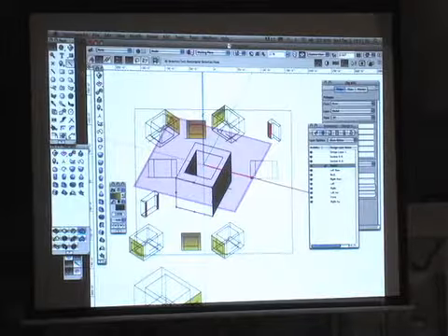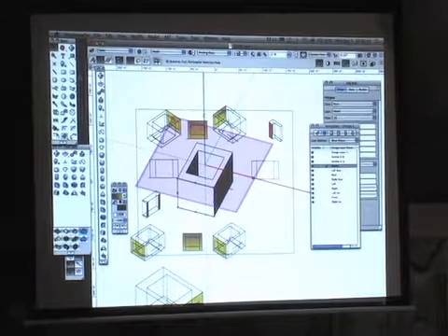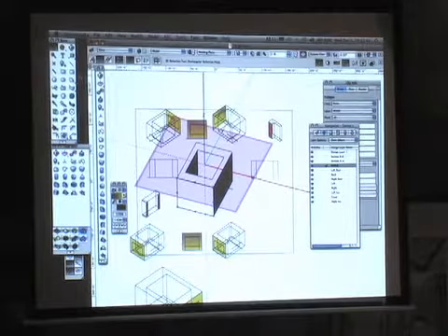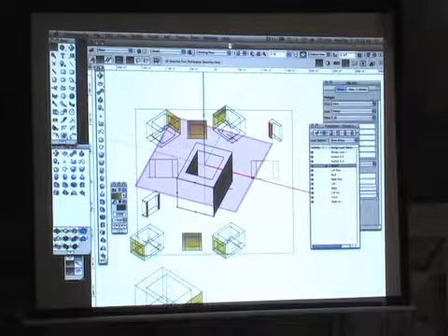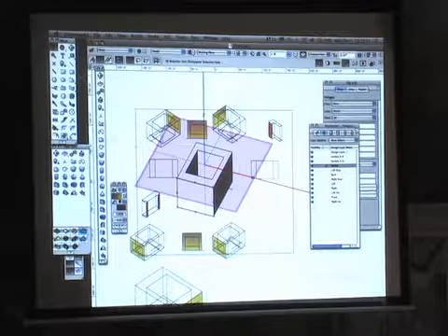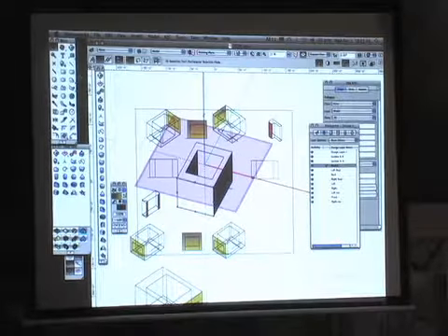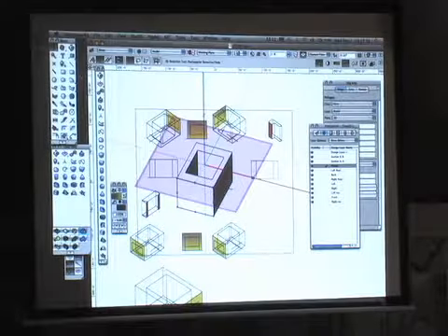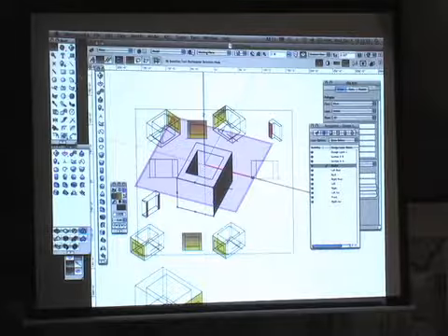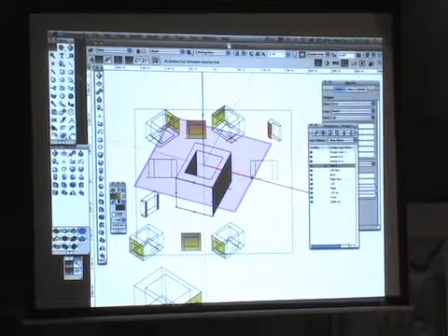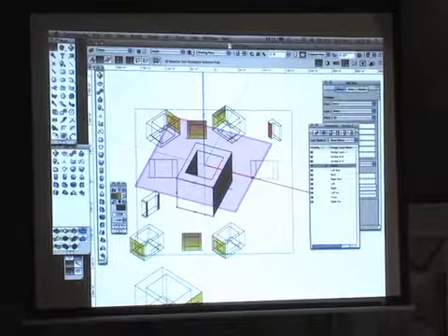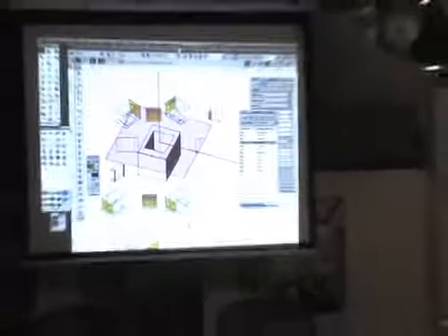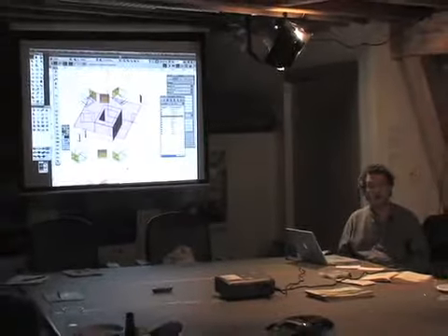Yeah, this is just a solid model, but if we had walls and windows, we could have our front elevation and see what happens if we move our windows over in plan. We'll see what's happening at the same time with the design layer viewports, instead of having to flip to the front view, flip back to the plan view, and back and forth. So with the design layer viewports, we're able to look at the model in different orientations, and as we apply our gradients or hatches to the model, they show up in the other viewports as well.